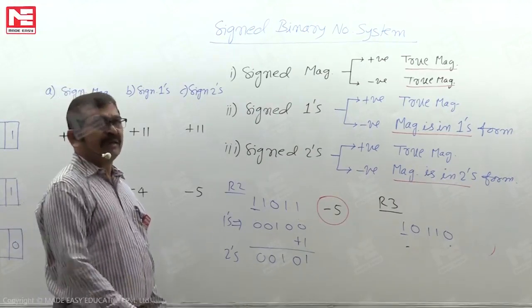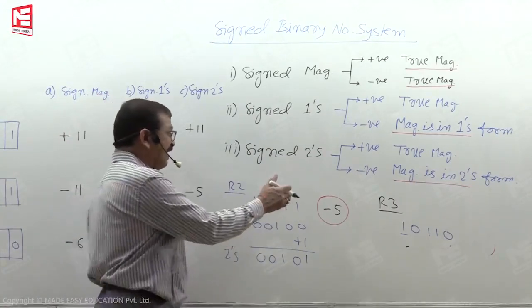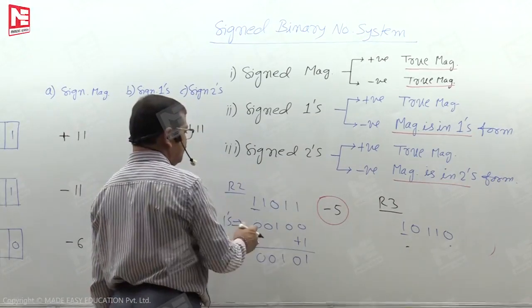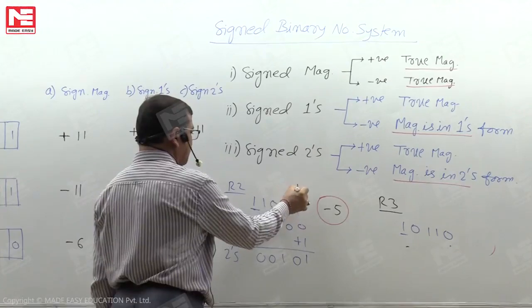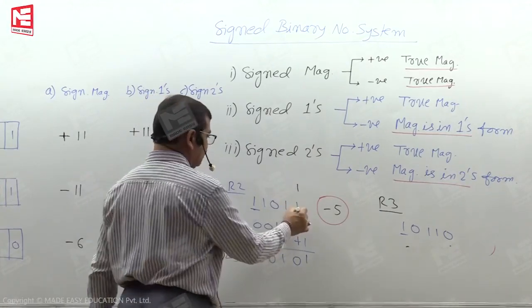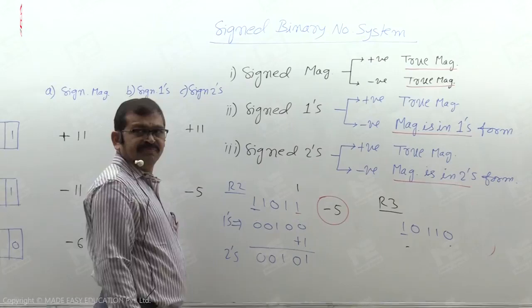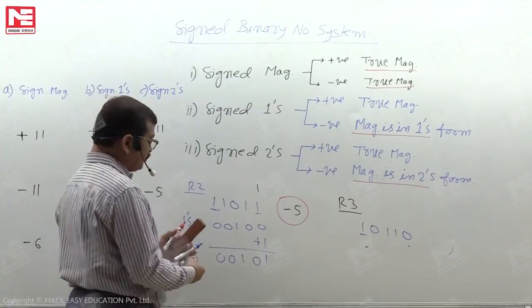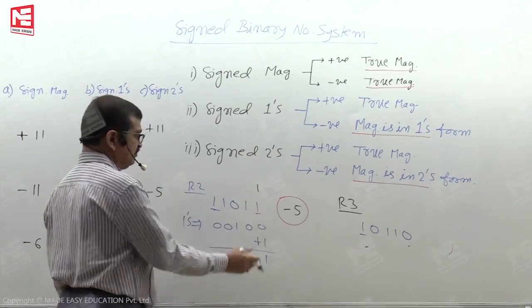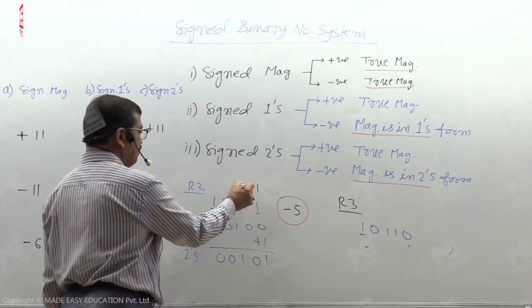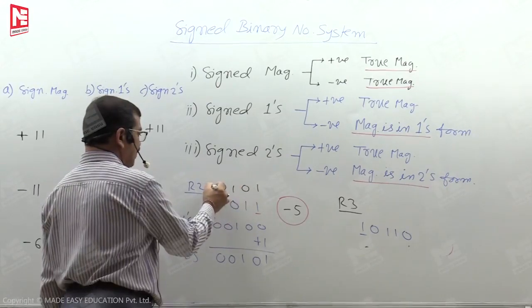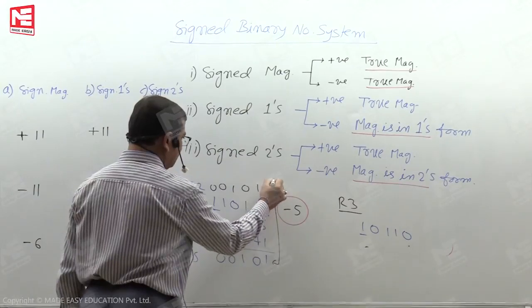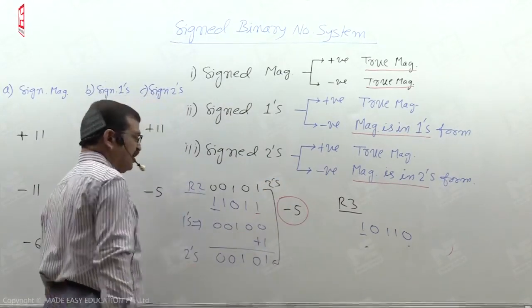Scan the number from right to left, keeping the bits as they are until we read the first bit that is 1. After reading the first 1, we perform bitwise complement on the remaining bits. Effectively, this is the 2's complement that we get conventionally.